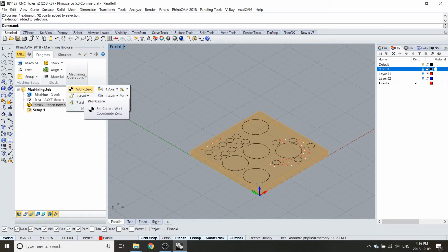Under the Machining Operations dropdown are milling operations for various forms of cuts. The commands are grouped based off the number of axes that they will operate within. Relevant to the CNC machine are the 2-axis, 3-axis advance, and the holes commands. Clicking each dropdown will show specific operations relative to the group. Once the command is selected, parameters for the milling operation will need to be entered. As each type of axis-based milling operation has slightly different parameters, we'll address their workflows in separate videos.